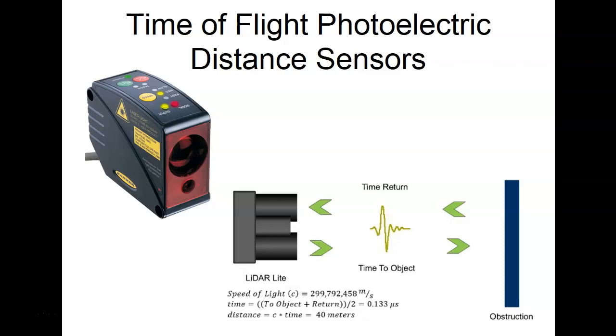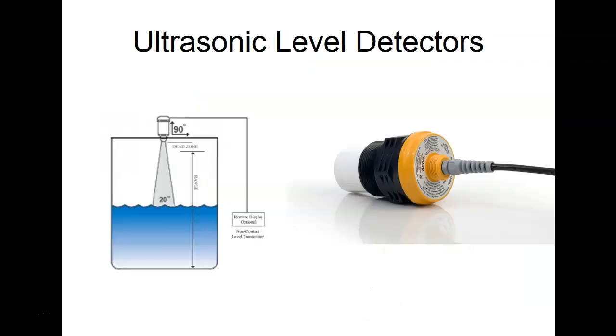Now remember, these guys are going to depend on what? Like ultrasonics. What does ultrasonics depend on? Yeah, but it also depends on the shape of the object, right? So usually ultrasonics is looking for a fairly flat surface, and then of course how much energy the surface it's hitting absorbs. So this guy would have problems with extremely dark objects, right? Because it would absorb more light and reflect less back. But lighter colors, this guy would have no problem with them. Of course, here's ultrasonics.